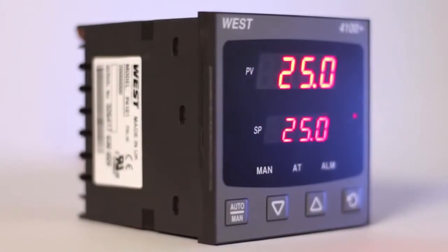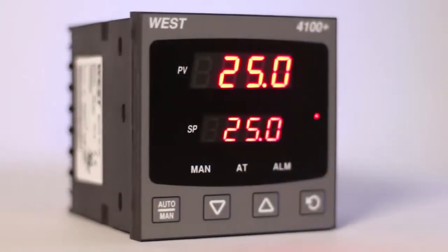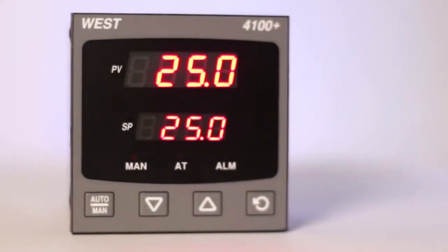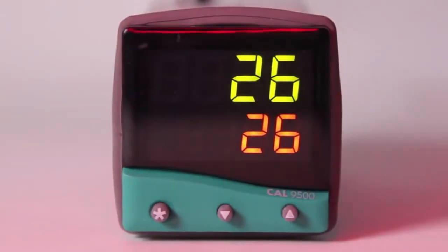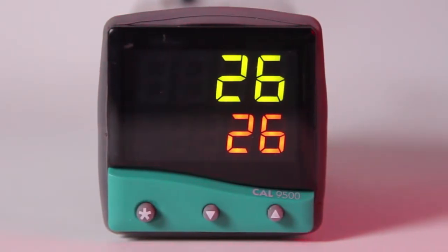A proportional controller doesn't just turn its output states to on or off, it can adjust them anywhere between 0 and 100% of available power. The direction of output is still important with proportional control. With reverse acting, the output is slowly moved from 100% through to 0% as the process rises. With direct acting outputs, the output will move from 0% to 100% as the process rises.